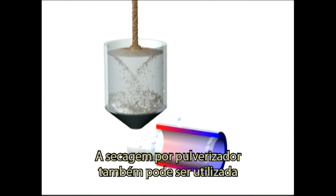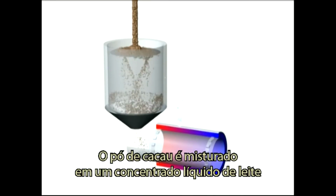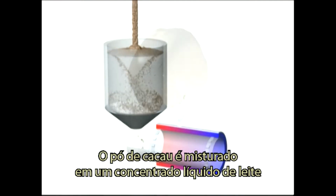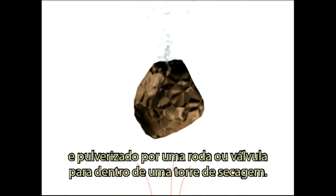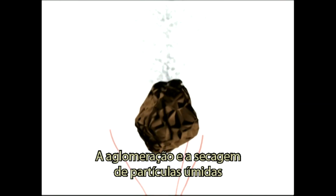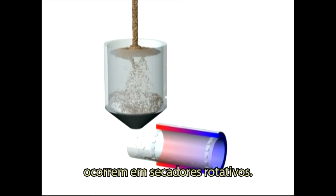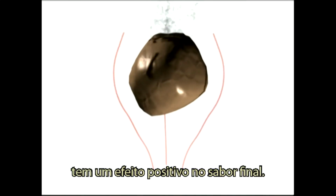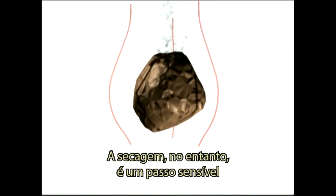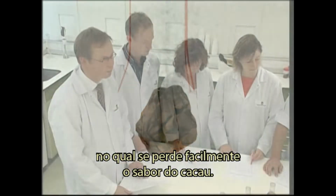Spray drying can also be used for the preparation of cocoa mixes. Cocoa powder is mixed into a liquid milk concentrate and sprayed by a wheel or nozzle into a drying tower. Agglomeration and drying of wet particles takes place in a fluid bed or rotary dryers. Here, the mixing of the cocoa and milk prior to drying has a positive effect on the final flavor. Drying, however, is a sensitive step, where cocoa flavor is easily lost.